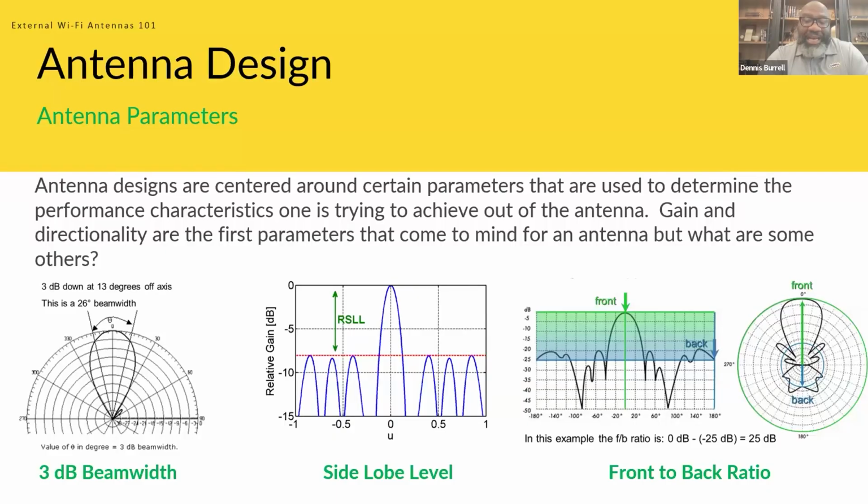So in a stadium design, for instance, if you're doing a side-to-side design where you have antennas on a handrail or in an enclosure in the handrail, and you're pushing to a specific section, you want to push the energy to that section to the right, and then the back lobe, you want it minimum to that section going to the left, because there's going to be another antenna covering that section.